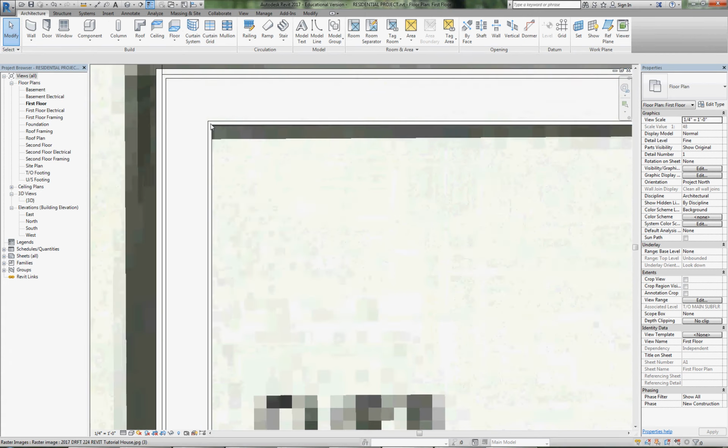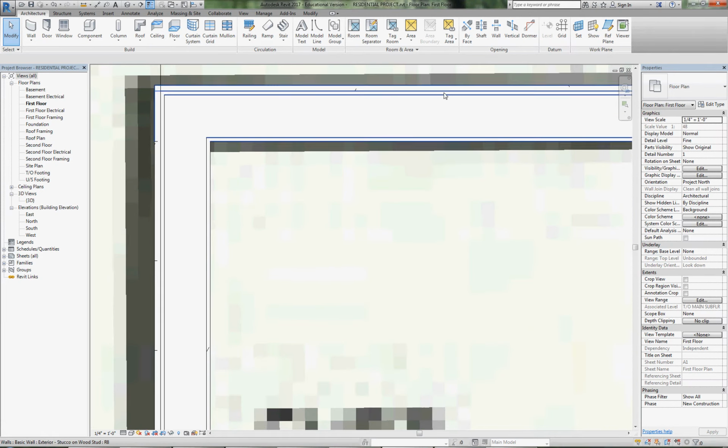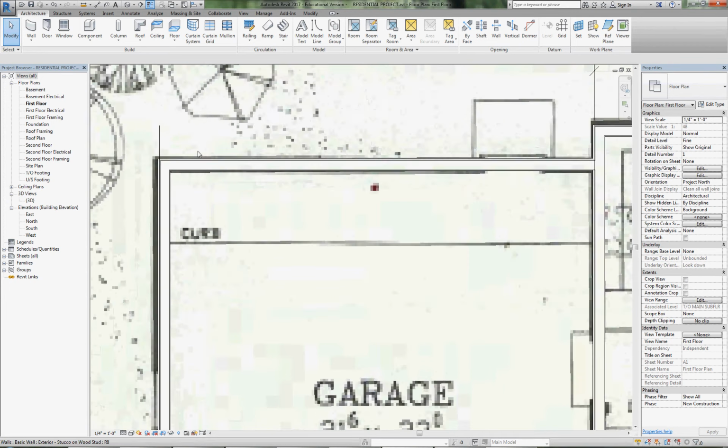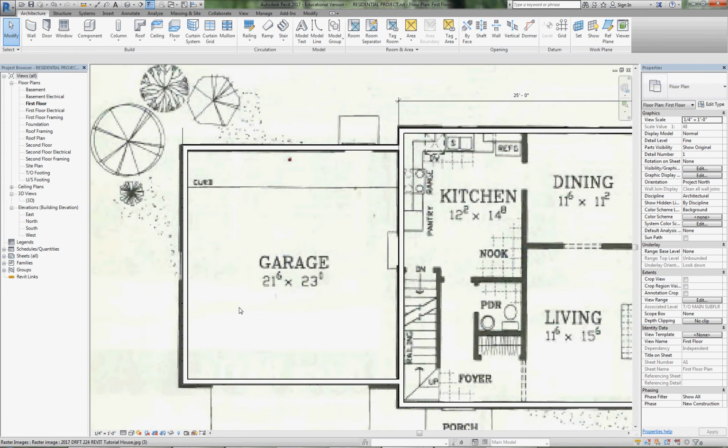Now, by choosing the correct direction for the exterior to go, for example, on this horizontal wall, the exterior is on the top half. That's where the stucco is. Once we have that, it automatically follows through for the rest. So those are all set. Now, to edit walls, unlike AutoCAD where we typically draw things exactly where they need to be, here we place the number and position of the walls in a preliminary state, and then we can finalize them with dimensions.